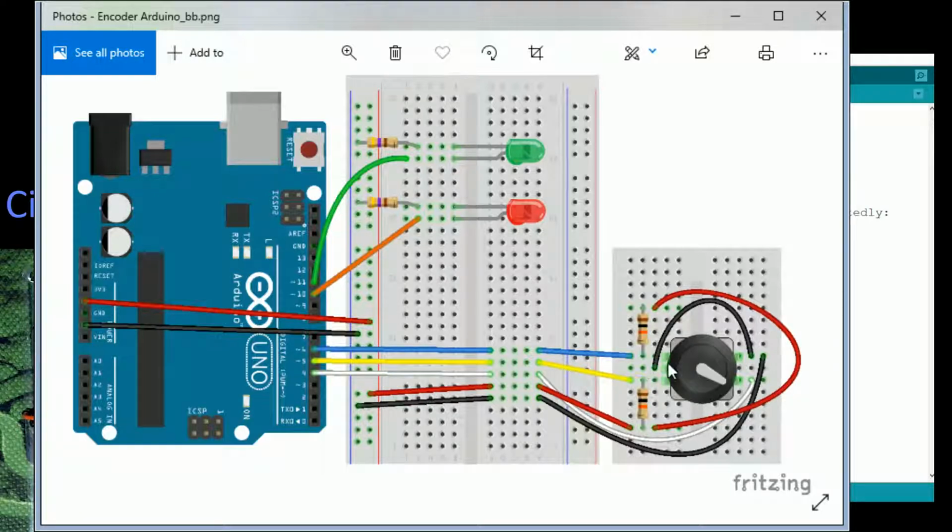Again, there's the center wiper, which is connected to ground, and we have power to the outside resistors. So if we're not making contact, this is high, and if we are shorting, it goes to ground. So we see pulses happening. It gets that reference voltage coming in on 2 of the input pins. I just happen to have them connected to 4, 5, and 6: 4 for the switch, 5 and 6 for pins A and B.